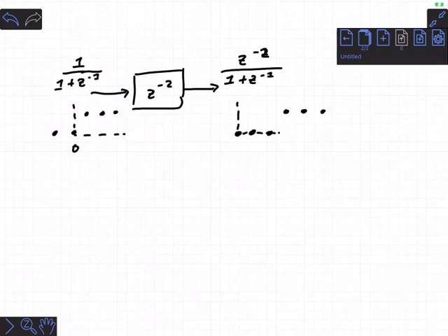It's telling us that, just like the Laplace transform, I can think of a thing in the Z domain as being dual purpose. When I show you some Z notation, up to now, I've said, oh, that's a signal. That's a thing that is sampled at certain points. That is a signal. But it's also a machine, or it could have been a machine. It's also a thing that does things to an input that it is multiplied by. And when we have it in this mode, we think about that as being the transfer function of a system.